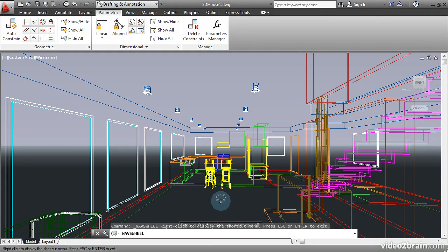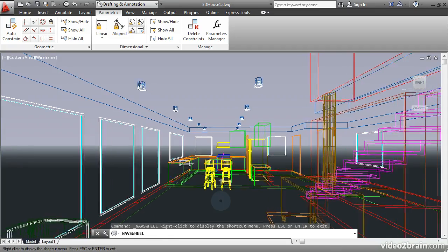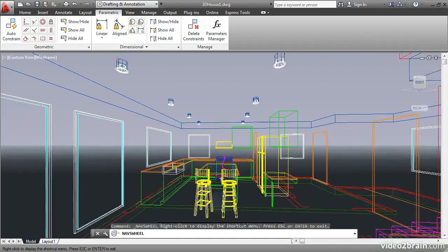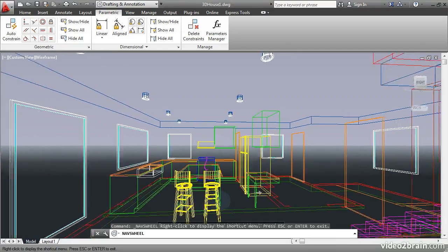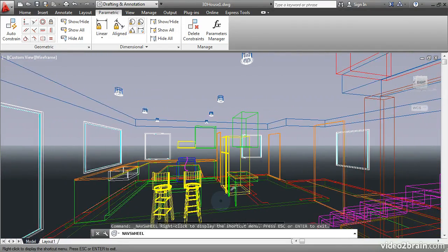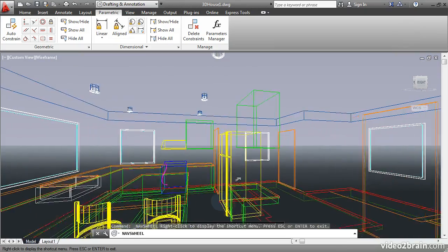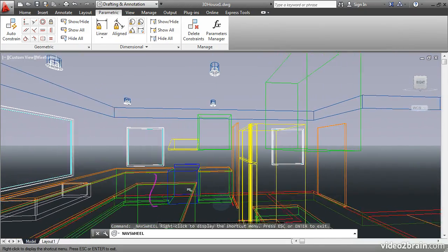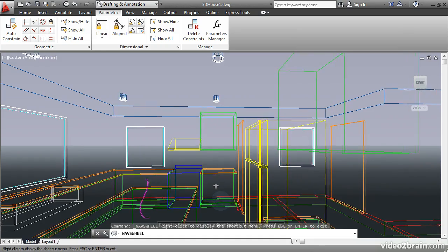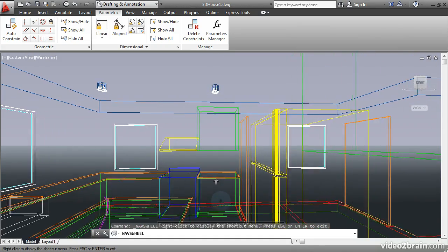If you move the cursor up relative to that point, you will start walking forward. Try that again. Click and hold on walk on the steering wheel, and then drag the cursor to the right to rotate right. Drag it up to walk forward. Drag it left to rotate left. See if you can walk in this area between the kitchen island and the refrigerator.